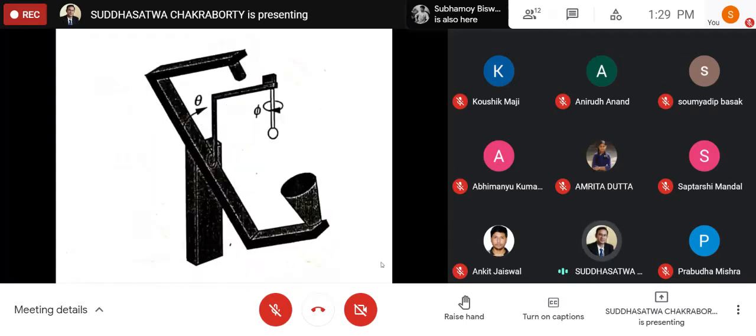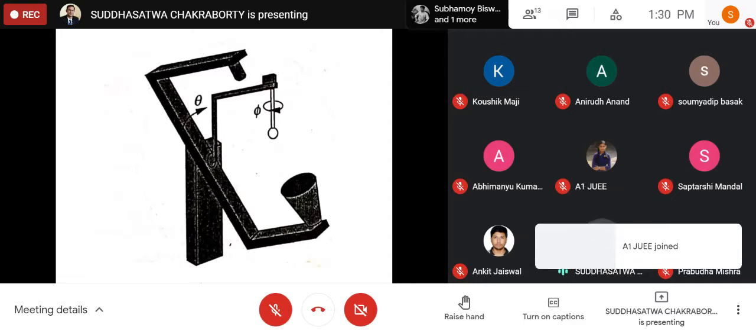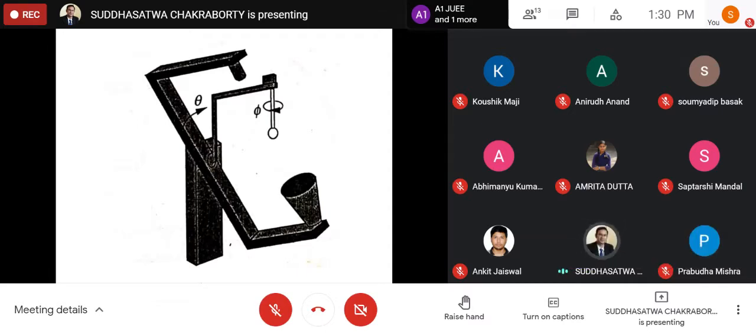Okay, so that is the idea of this case. In this type C meter, we are rotating the source in the horizontal plane to get the different C angles, because we already talked about it: the C angle is my horizontal angle. It's a vertical plane, but it's a horizontal angle actually. So how can we achieve the different horizontal angles? By rotating the C. And if we rotate the sensor in the vertical plane, that gives a different series of gamma angles. That's how we are finally recording all the data.